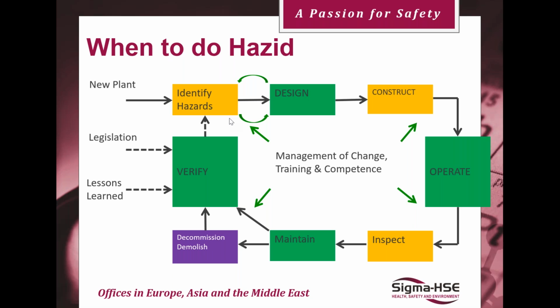Once we've got a process that we're looking at, once you've got something like a process flow diagram or a block diagram that might consist of just boxes saying this is the reaction stage, this is the separation stage, this is the final product storage stage, we can start to put some detail into that. If you know the conditions of temperature and pressure and what sort of flow rates you're looking at, you can then interrogate that design, and the HAZID is the point at which this is most appropriate, because it is appropriate for the level of detail that you have about that design at the time.